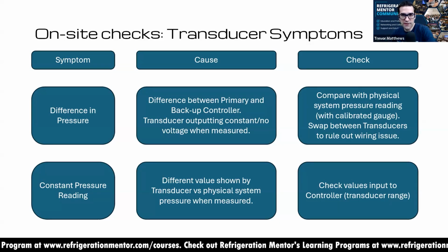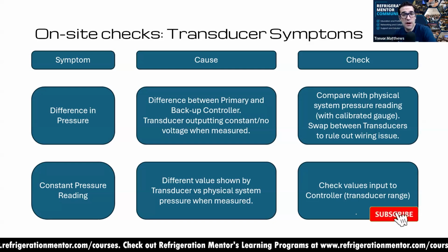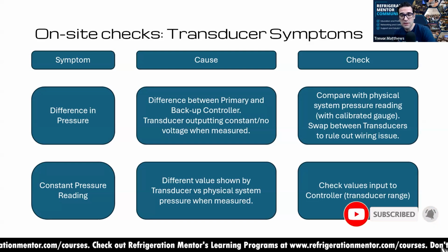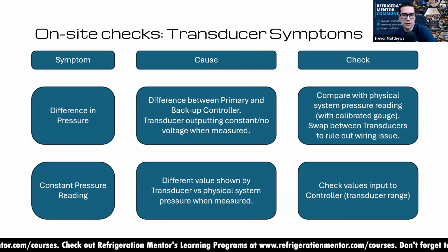And I've talked to a few manufacturers who do a lot of support, and they've seen a lot of technicians cut valves out or replace valves for what was actually a transducer issue or a wiring issue to a transducer. John, do you have any experience with that?